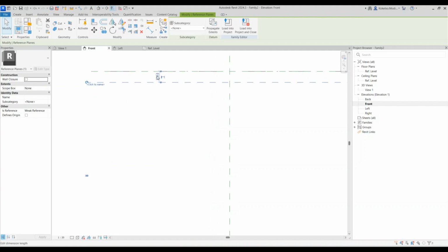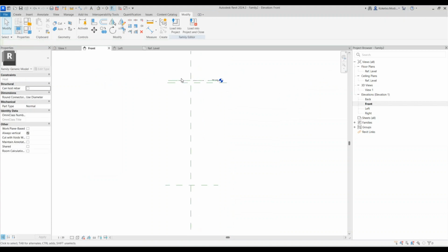So the depth of my bearing is gonna be 120, or let's make it 60 for the concrete plinth, and then for the two plates are gonna be 40, so 20 each, and then the epoxy is gonna be let's say 40 again, so it's gonna be 140.